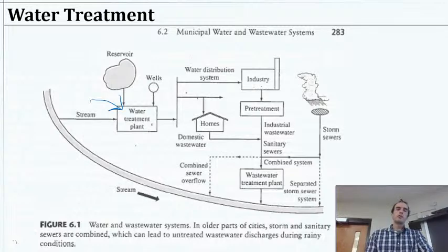Now, sometimes industry may also elect to pay to hook up to the sewer and send their wastewater there. For some industries that might be fine. Maybe you have a fiber recycling plant, recycling a bunch of cardboard to make tissue paper or something like that. They're going to have a lot of fibrous, carbon-containing stuff in their wash solution, and there's a good chance that typical microbes can eat a lot of that and create just bacterial cells in place of the junk that was in there.